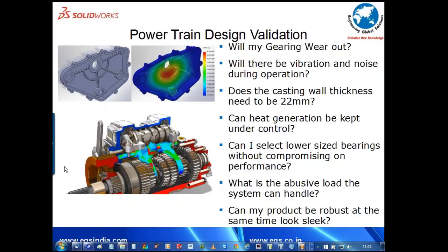You do not give the design load. The moment you give the design load, I have seen companies mistake it as operating loads and operate upon that, and the supplier pays through his nose in terms of warranty costs during the warranty period that he has provided to the customer.